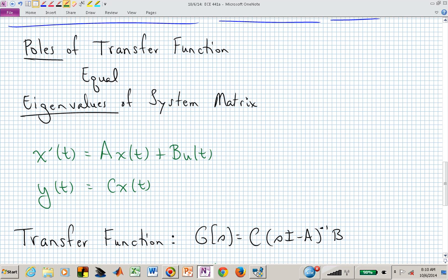And that means we don't have this direct connection, and you can hopefully start to visualize these block diagrams, and you do not have a direct path from your input to the output. It has to be filtered through some integration operations to eventually influence the output. That's a strictly proper system.